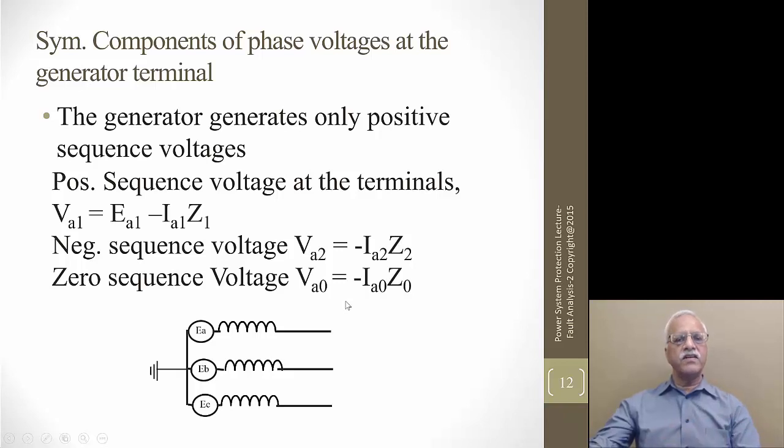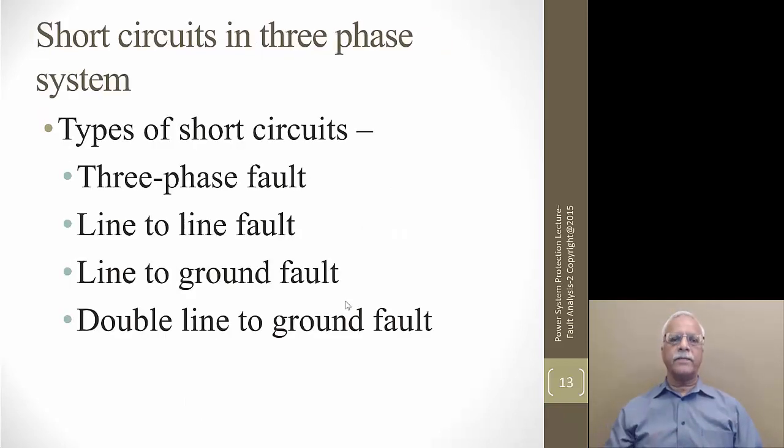So this concept we will use in the sequence networks, and instead of a generator, we look at the equivalent reduced voltage source and an equivalent impedance in series with that using Thevenin equivalence, and then we represent that and use it for our calculation.